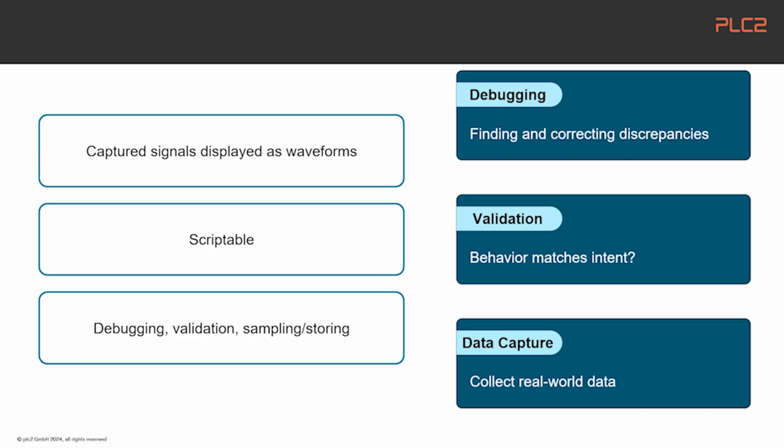Data collection requires the ILA cores, so the Integrated Logic Analyzer cores. And VIO cores provide observing states without capturing data. And this is quite important as it also requires some resources in the PL design, like block RAMs.